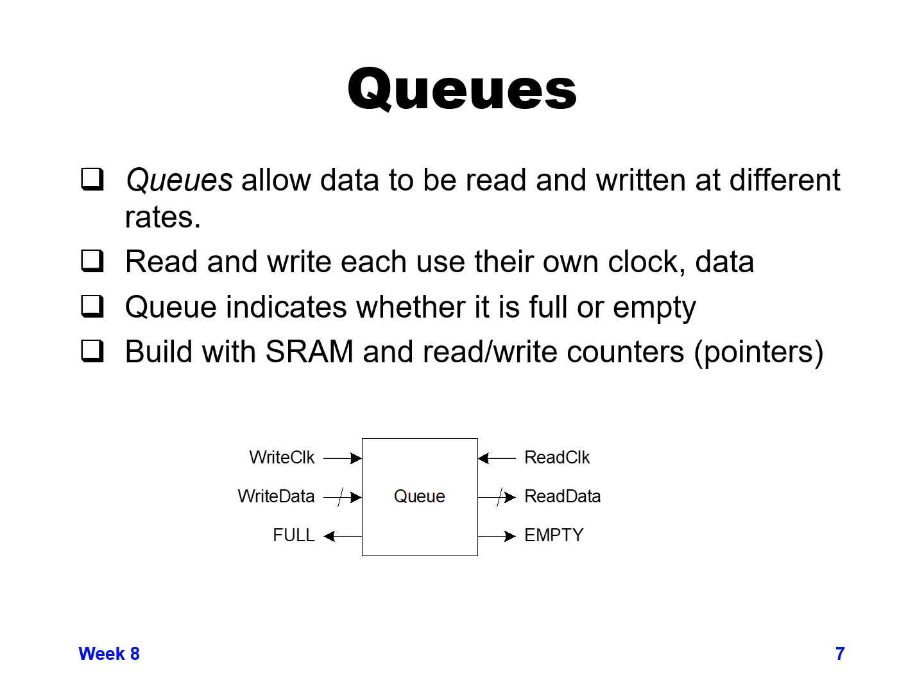And you could wind up building a queue using an SRAM, for example, and then you just create read and write counters and pointers as part of your additional logic around the SRAM. There's obviously other ways you could build it as well, with just an array of flip-flops, for example. It just might not be quite as dense as an SRAM would be.